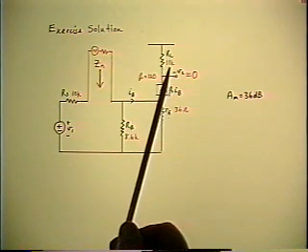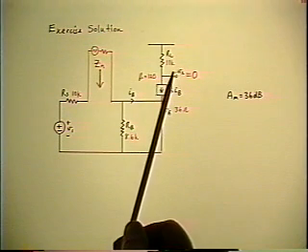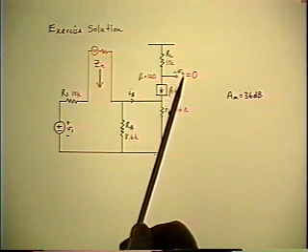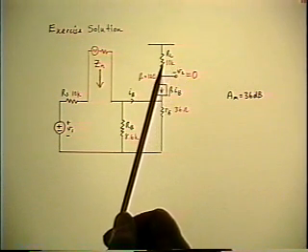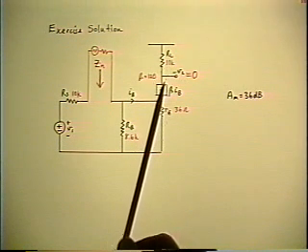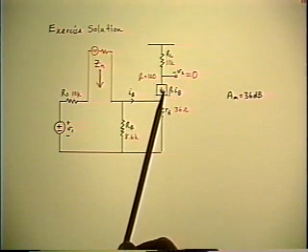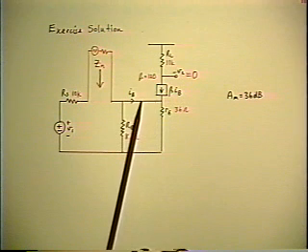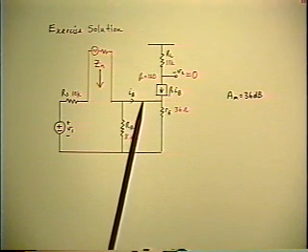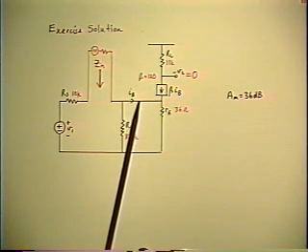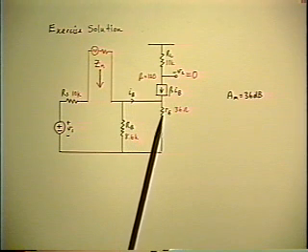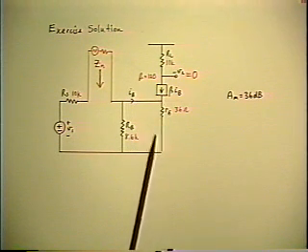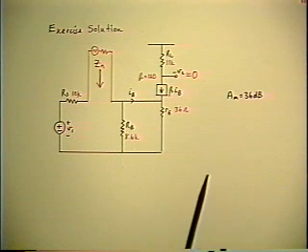Okay, let's follow it through. Propagate the null back to the second source. V2 is 0, therefore 0 current in RL, therefore 0 collector current, therefore 0 base current. But that's not all. Also 0 emitter current. Therefore no drop across RE, therefore no drop across RB.